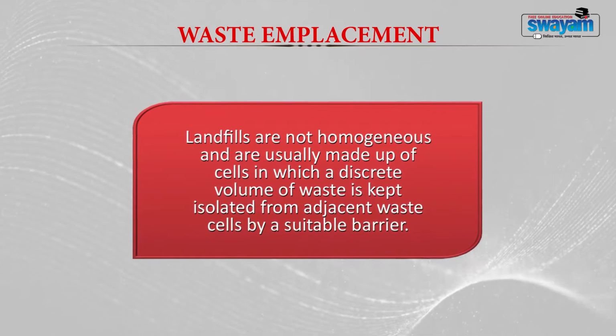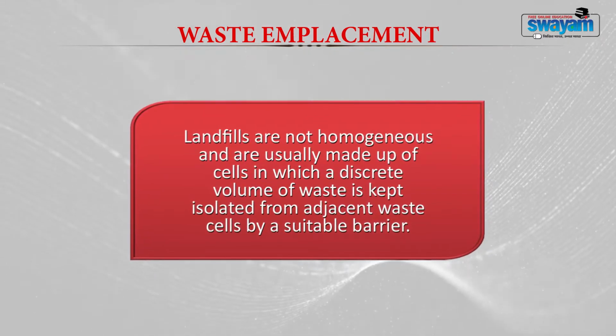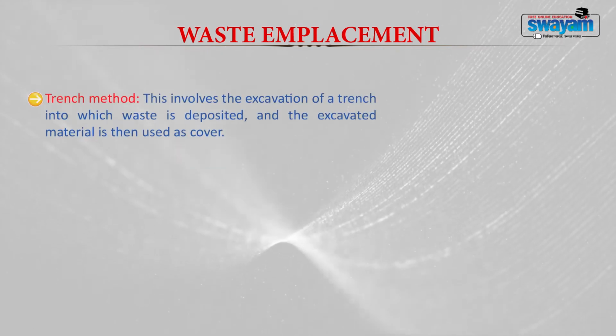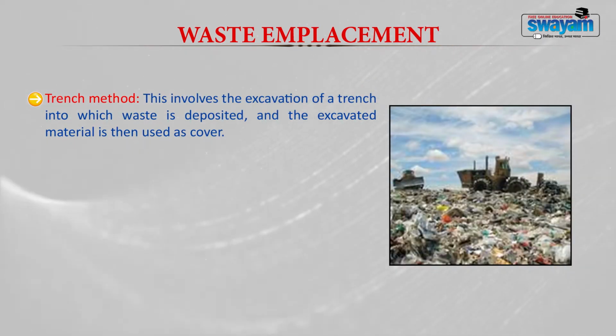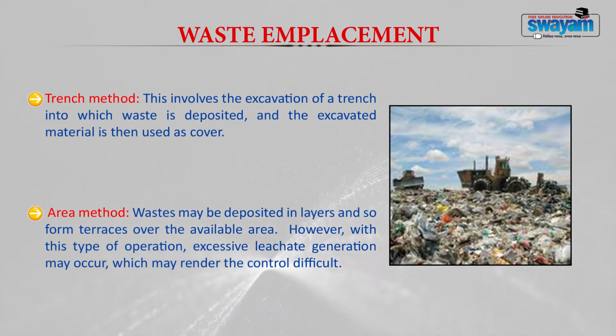There are different methods of waste loading in a landfill. The first one is the trench method. The trench method involves excavation of a trench into which the waste is deposited, and the excavated material can then be used as a cover. The second method is the area method, where the waste is deposited in layers.